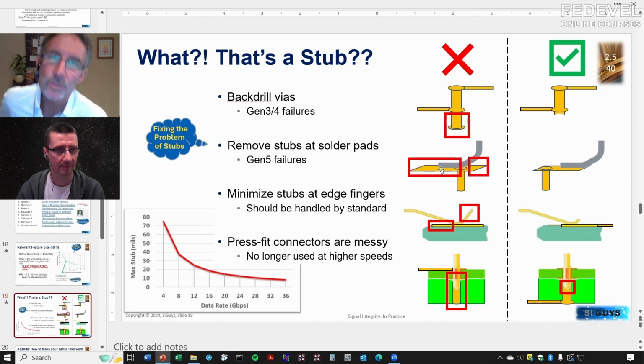Okay? So because of the max stub I showed in that other table, well that thing might be 50 mils long. But you can't do that at Gen 5. Now, did it totally stop transmission? No, it didn't. But the bit error rate went way up. Okay, so in product test, people are like, wait, something's going wrong here. We have generation 5, but it works like generation 2.